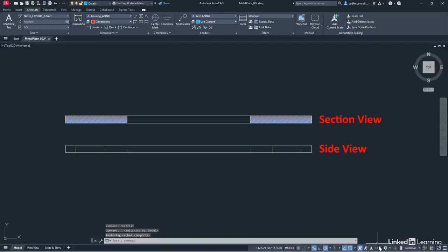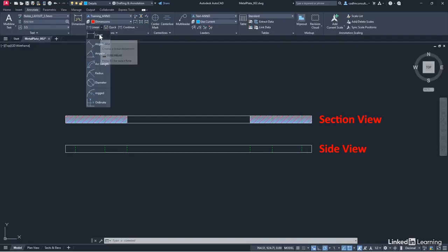It's down here on the status bar. Click on the flyout there. There's your annotation scales. At the moment it's 1:1, so they'd be incorrect. So we need to go to 1:2. Our annotation scale is now set at 1:2. So anything we create in the model tab will display in that 1:2 viewport in the sections and elevations layout tab. So we go up to the dimensions panel, click on the dimension types, and we want linear.